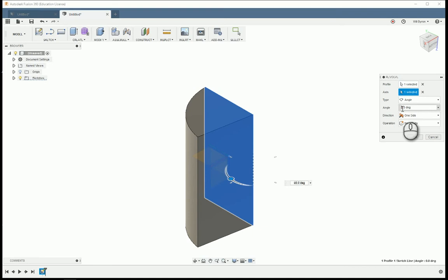Yeah, we'll make it 90. A 90-degree turn and 3D object off of a face. You can do whatever angle you want. You can do a couple different options, like full, which is 360. Two would be if you have a face. So imagine you had a rectangular face here, a rectangular face here. You could use the revolve tool and use the two function to go from one rectangular face to the other without having to worry about, well, what happens if I've gone too far? It's going to cut off my detail.